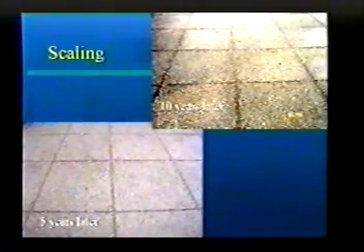This is 5 years later, and this is now 10 years later, and we have a very nice exposed aggregate finish on our sidewalk. Now if I were to do petrographic analysis, I could see the high water cement ratio at the top surface, and I could see a progression of water cement ratio as you go down through the concrete. So yes, I can tell that. Now I happen to know exactly what happened here, but this problem could be caused by other things. Maybe it's just bad concrete, maybe it's overfinishing. But if you do your lab analysis, you can come to exactly the source of that problem.